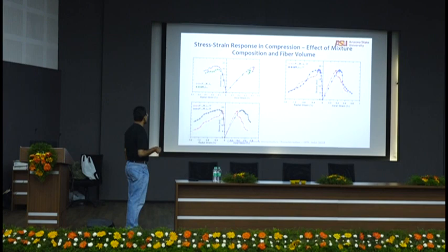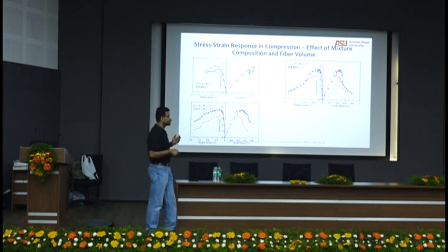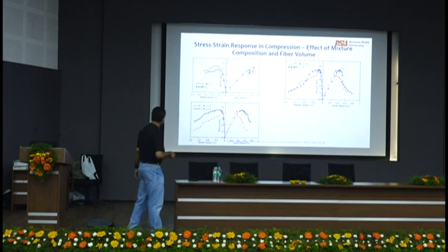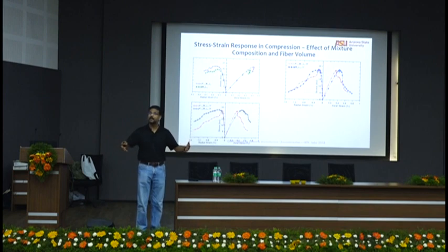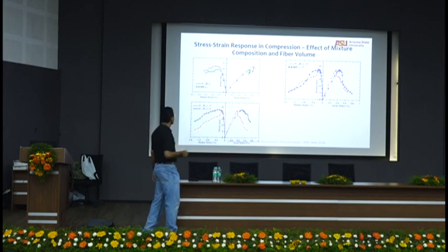Now if I put in 1% fibers, the story completely changes. Look at how the axis here, instead of 0.5, gets up to 1. Do you see the post-peak behavior in compression and the post-peak radial behavior in compression? So with fibers, you get extremely high ductility. Look at 1% radial strain, 1.2% radial strain, which means you're letting your Poisson effect take effect so much without breaking the specimen. The fibers are holding it together so that you can take much higher load.